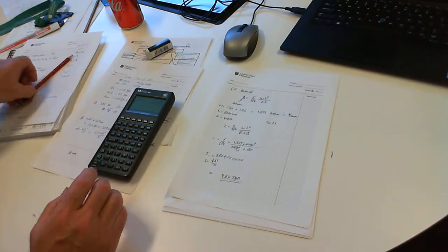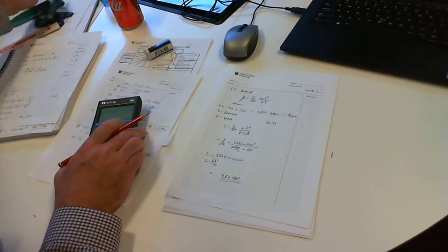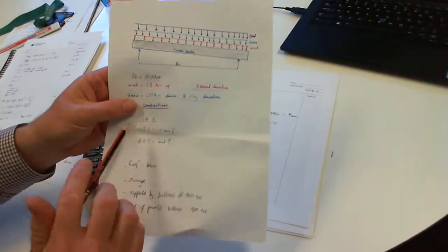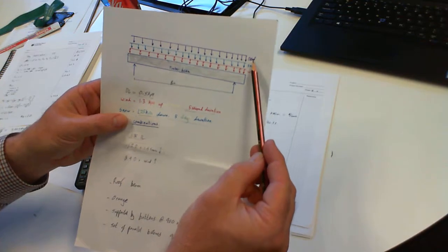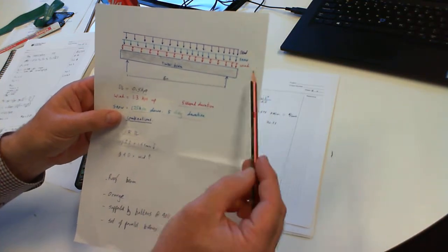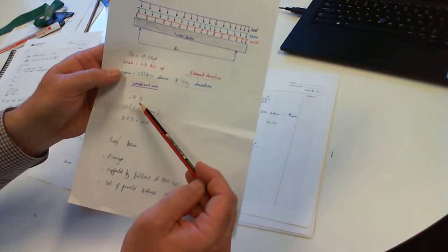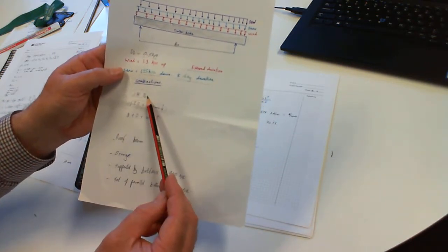Okay, part 3, just to check where we are. We had a timber roof beam, which looks like that. 6 meter span. It has a load of dead load, snow load, and wind acting upwards, which we're not considering at the moment. We have gone through the load limit states of 1.35 is dead load,